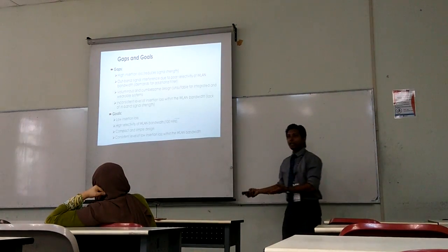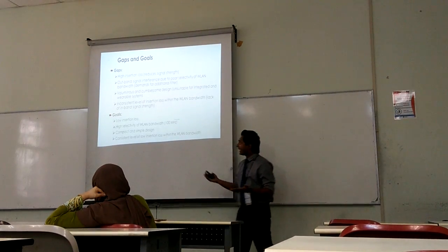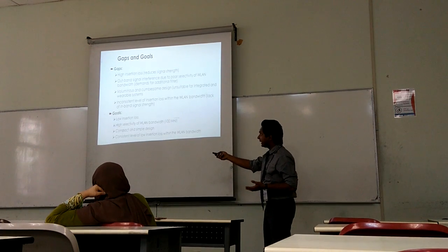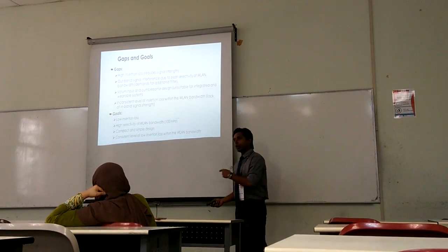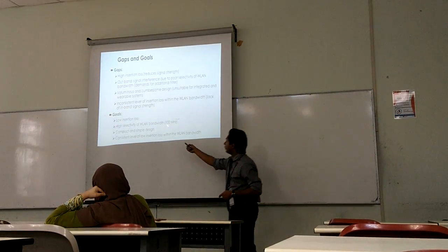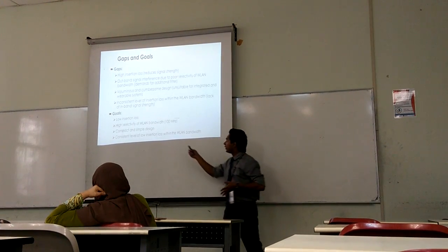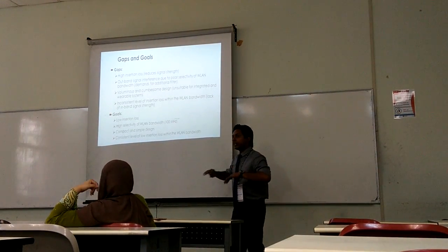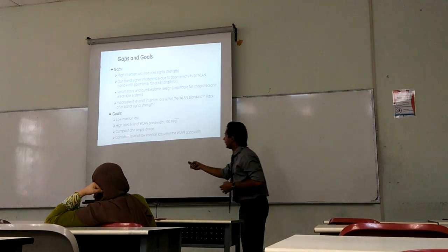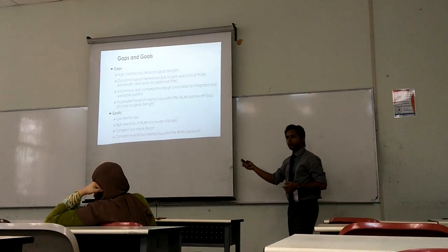So from there, we are proposing our goals. We are proposing a filter that can achieve all four things together. The first is the low insertion loss. This is our primary target. The second is the high selectivity of the WLAN bandwidth, as mentioned, 100 megahertz, which means we can sharply select this 100 megahertz band to reject the out-of-band. Also, the filter has to be compact and with a simple structure. And the last one is the consistent level of low insertion loss within the WLAN bandwidth.